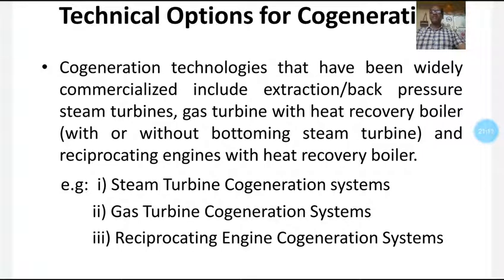Up to 85% of thermal energy can be utilized in this way to generate steam or hot water, which is the subsidiary requirement of various industrial and chemical process purposes. Electrical equipment distributes the electricity. Pipeline transport of hot water or steam is sent whenever it is required. So this is the technicality behind the combined power generation or combined heat and power generation.